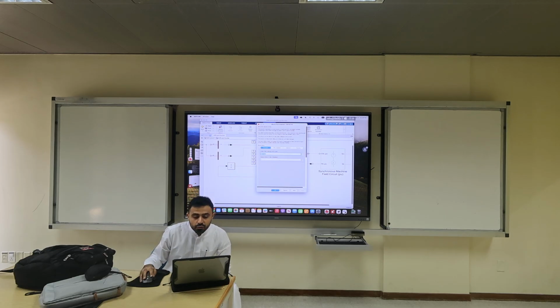For inherited discrete, no need to read more about these, but here is the general. The initial field voltage. This is EF at time 0. -1 is for inherited. This is the default setting. So put -1. It's a common thing in Simulink to put -1 for what? Default.